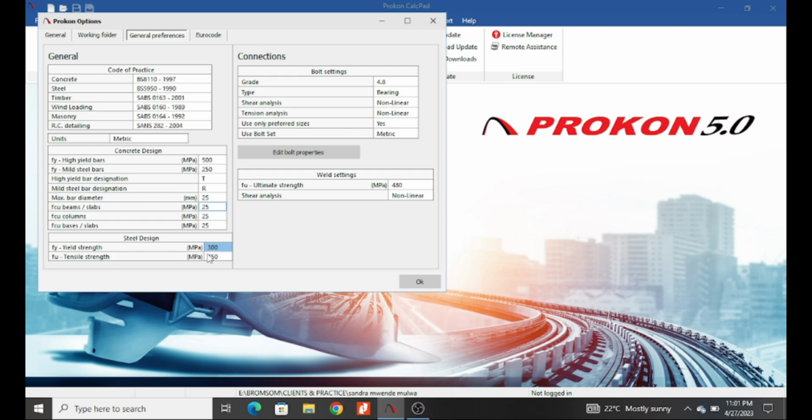Checking on site might give you trouble, because sometimes you might forget to give the instruction, or you might give the instruction but it is not followed. So it is always good to use a uniform class of concrete, so that even your foreman or your fundi, here we call them fundis, the laborers, the casual laborers and the skilled ones can always use the same class.